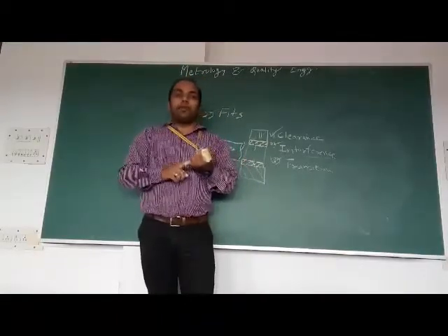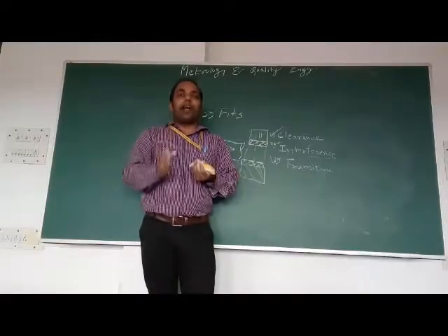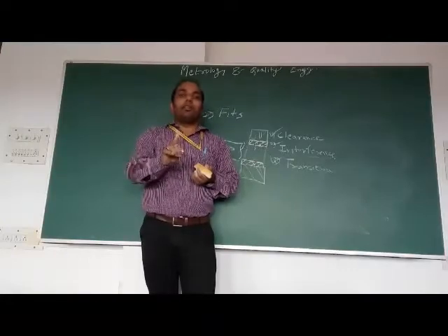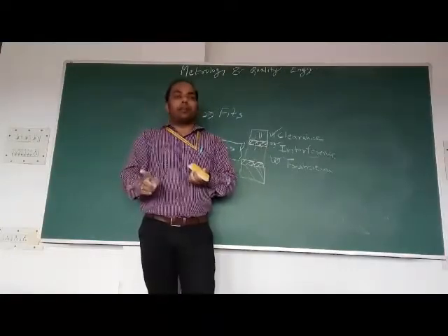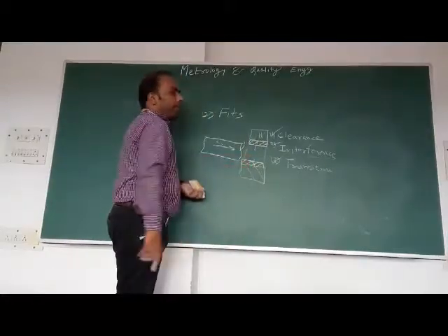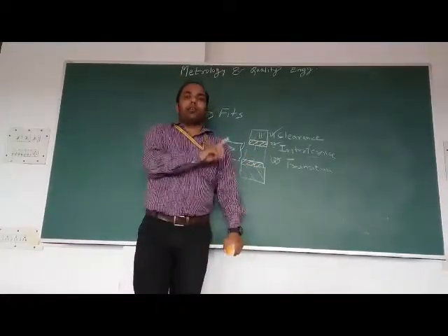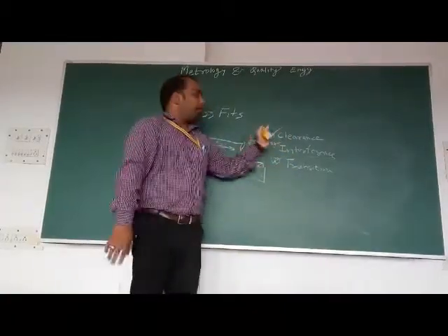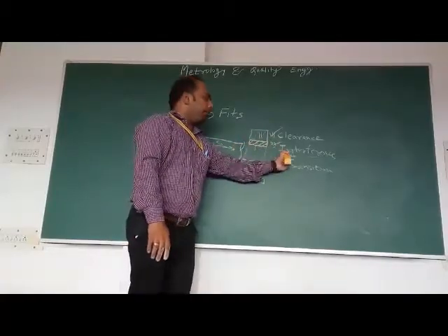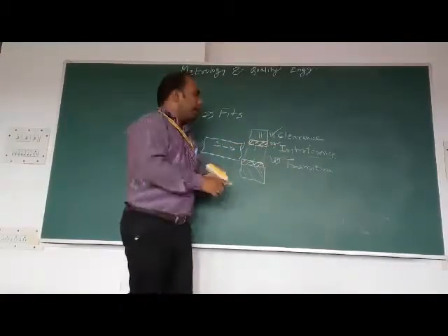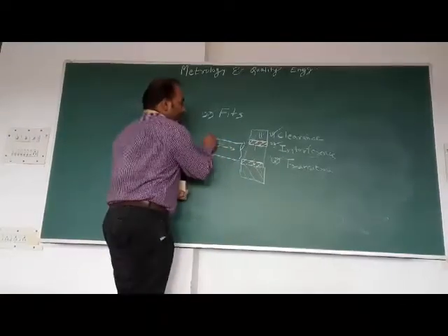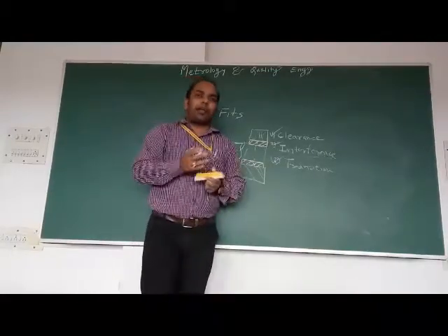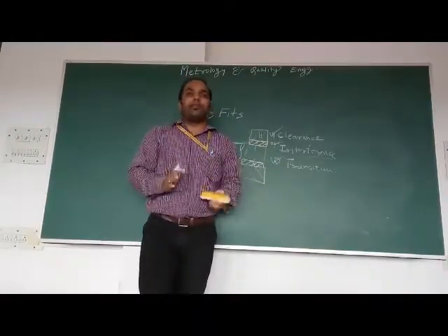Please do remember there are two systems of basis. First is the shaft basis system, second is the hole basis system. Shaft basis system favors minimum metal condition, whereas hole basis system favors maximum metal condition. Next to that were the three types of fits. Fits are totally dependent on the shaft and hole, and these three fits are clearance, interference and transition. Clearance will give easy go and out. Interference will create some sort of interference during joining, and this interference will be created at the maximum limit of the shaft and minimum limit of the hole. And transition, maximum limit of the shaft and maximum limit of the hole will create some sort of interference.